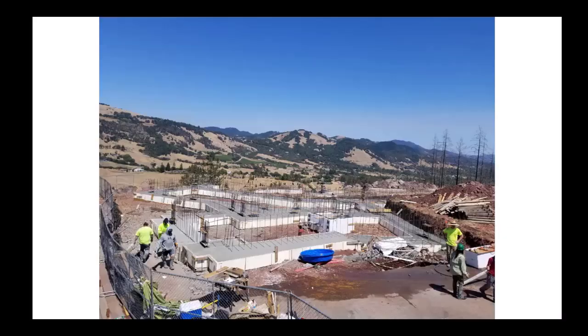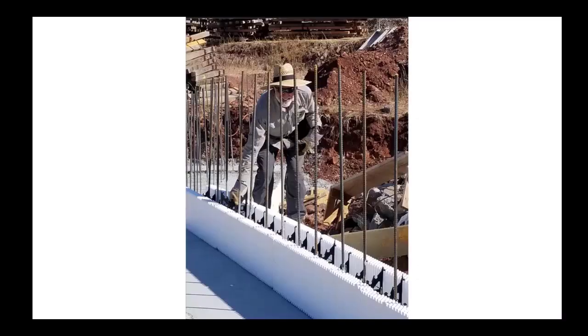This is the first floor row of footings that were done. This is the placement of the first row of the ICF forms. Again, there's the styrofoam, the brackets that connect them together, and the other piece of styrofoam. And those black brackets actually are the studs in the wall to mount whatever you want to mount to it, drywall, whatever it might be.